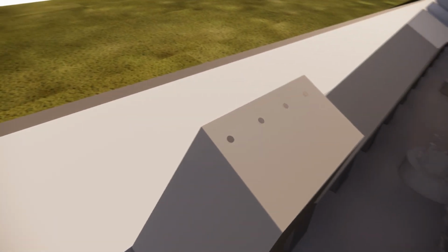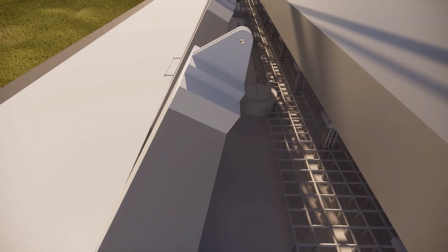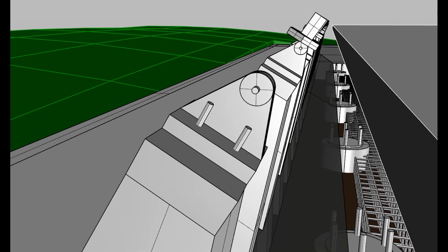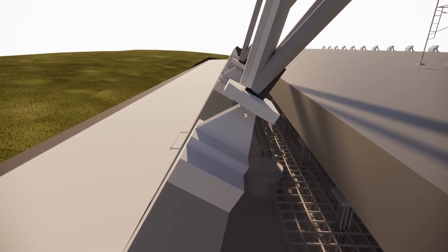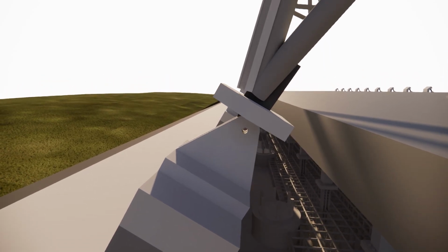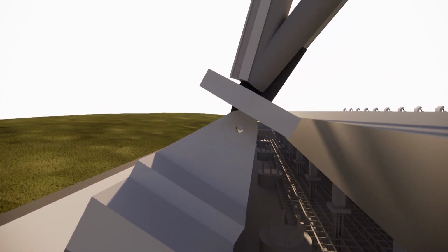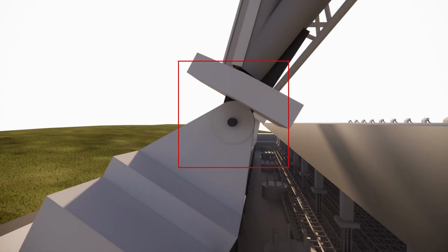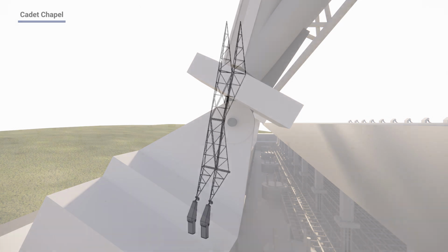Now let's construct the hinge support. We'll create a steel hinge base that matches the end of the support base and use bolts to secure them together. In order to connect the frame to the hinge, the end of the frame needs to be shaped into a ring. This ring is then fitted into the support and secured with bolts, completing the hinge support installation. Now with this setup, we are ready to withstand the load of the roof part.